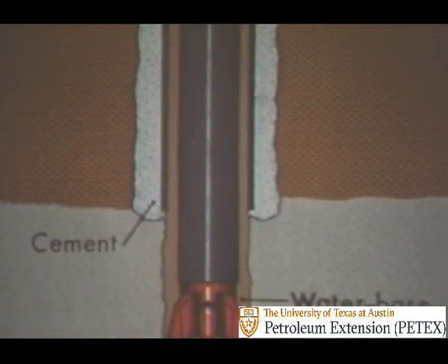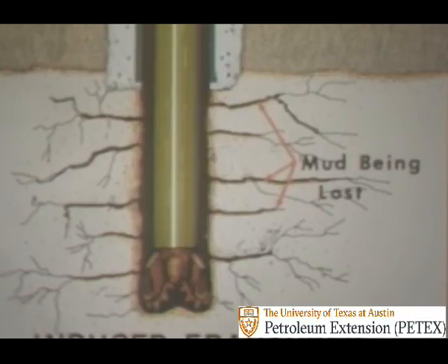Meanwhile, at the rig, drilling starts in the section below the cemented casing. Note that water-based mud is still in the hole. After drilling out a few feet, the blowout preventers are closed and the well is pressured up to test the cement job and to see if the formation can withstand the pressure without fracturing. If the formation does fracture, then mud flows out into the fractured formation and does not return to the surface. In other words, lost circulation occurs. Of course, lost circulation is never desirable, but it's especially bad with an oil mud because oil mud is so expensive.